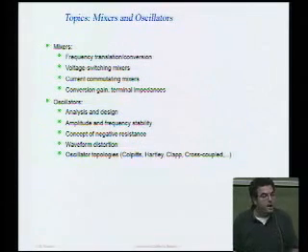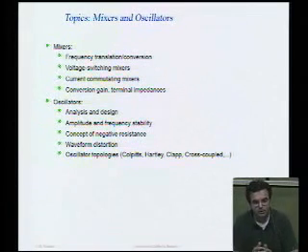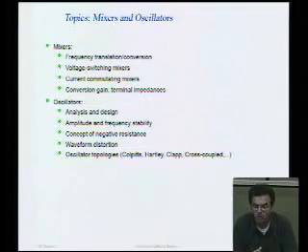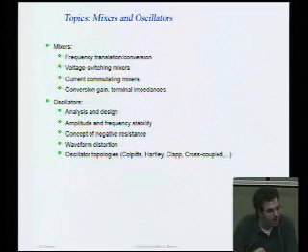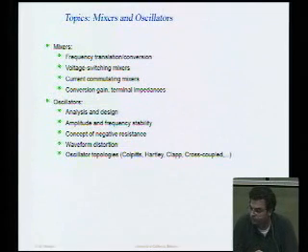Turns out that SPICE, actually standard SPICE, is not a very good tool for analyzing mixers. It's very slow. There are better tools for analyzing mixers, namely harmonic balance simulators and periodic steady-state simulators, such as Cadence Spectre RF. And that's when we're going to learn about these simulation tools.